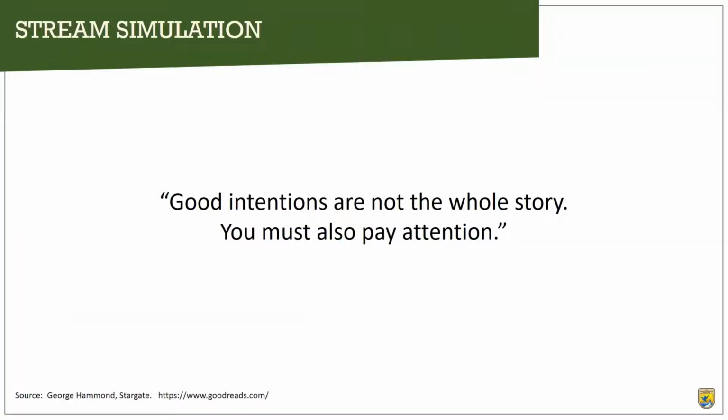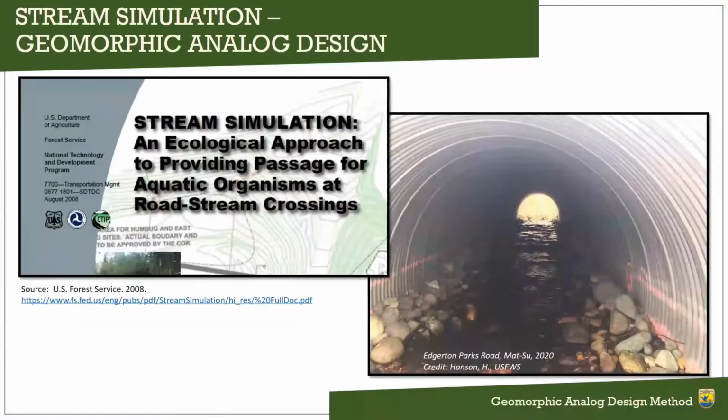So good intentions are not the whole story. You must also pay attention, and by pay attention, we mean pay attention to what the channel geomorphology is trying to tell you. Many guidelines and criteria don't really use geomorphic design principles. Here's one that does. This culvert that you see on the right was designed using the U.S. Forest Service guidelines for stream simulation, and these are geomorphic design guidelines.